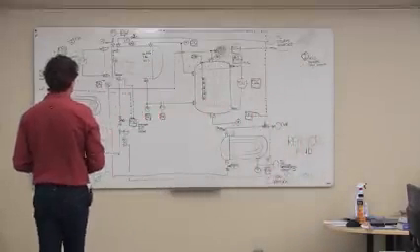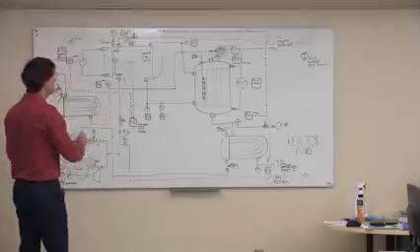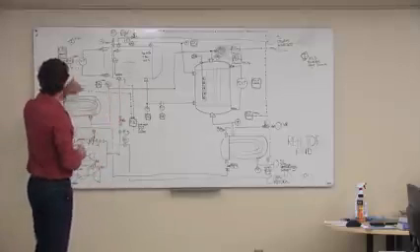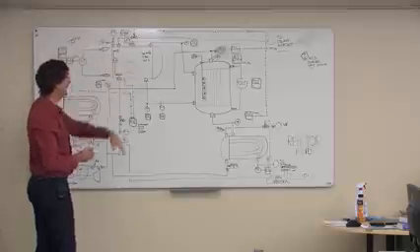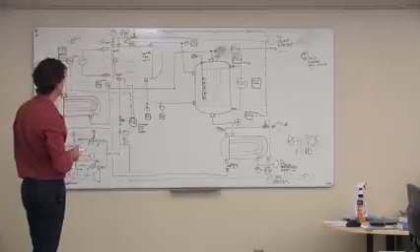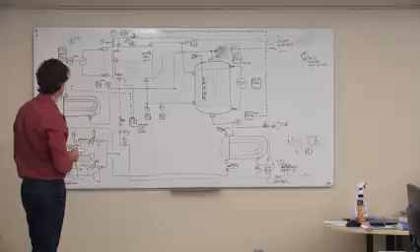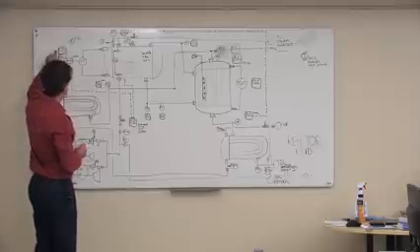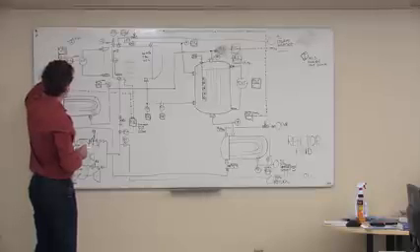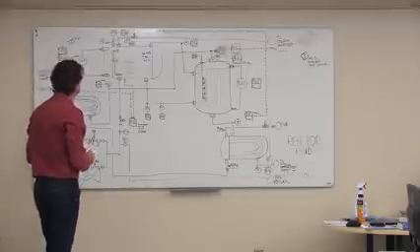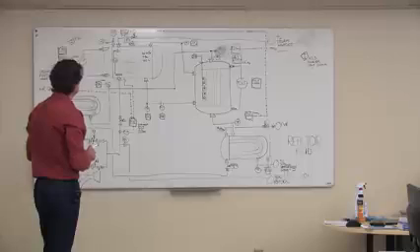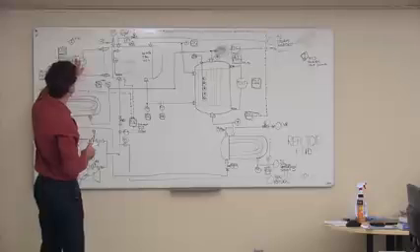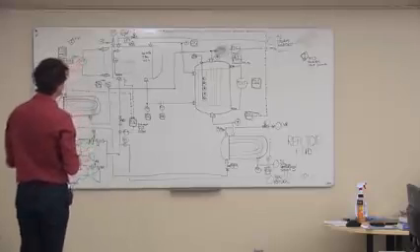And then however we decide that we're going to actually do that shutdown, basically there would be another interlock like that on that other P&ID that gets that signal and activates it. Okay, so we've got a low level here. We might actually want to have a high level. We've got a high level just in software here. So that might be good enough.